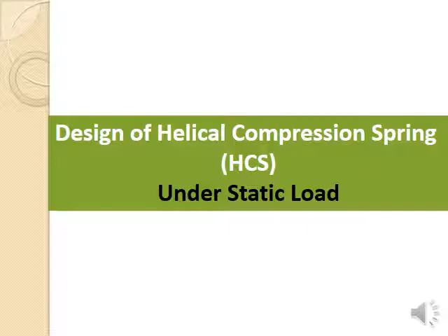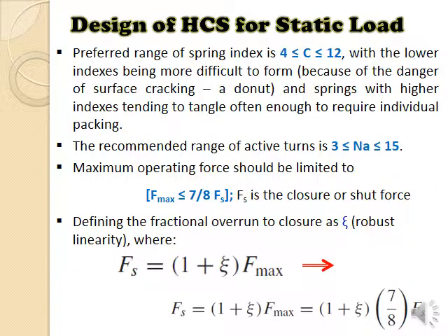So this is the design of helical compression spring. Now, a few things that we have to take into consideration while designing the helical compression spring. One is about the spring index. This spring index has to be between 4 and 12.